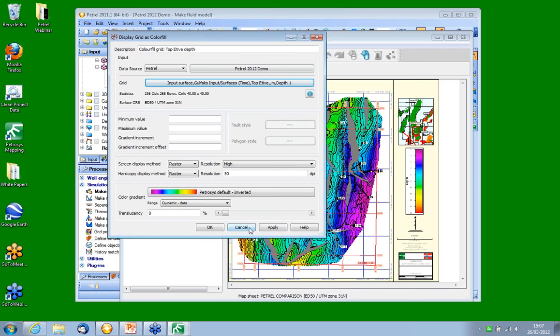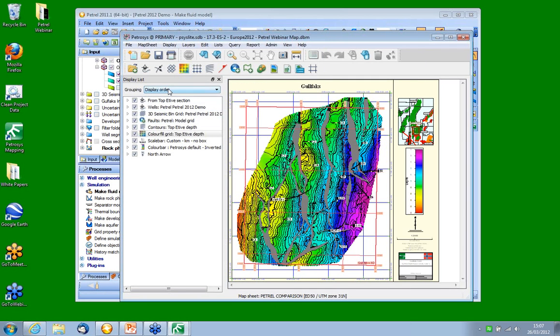So all of this data on our map, this particular map we've got displayed, if we choose the data source, we can see that we have well data, seismic bin grids, which we can scroll on and click on, faults, and the colourful grid. This is all coming from Petrosys, and the value of doing this directly is twofold, really. First of all, we can make the high quality, presentation quality final maps that we see here. It's typical of Petrosys, and also when making the maps, we can do coordinate conversion on the data.